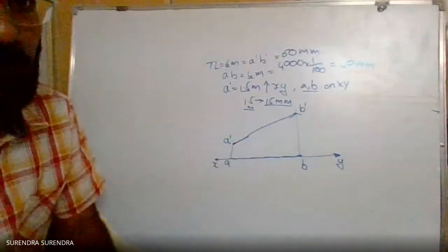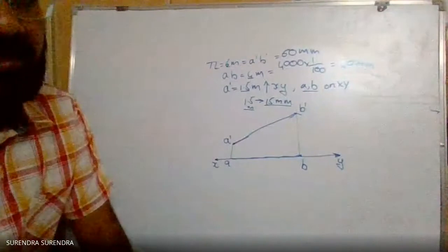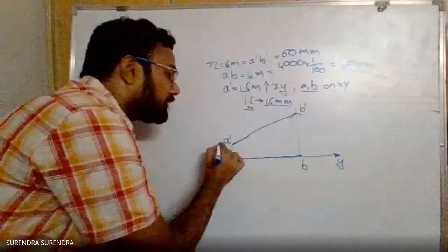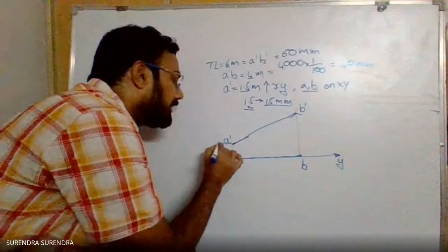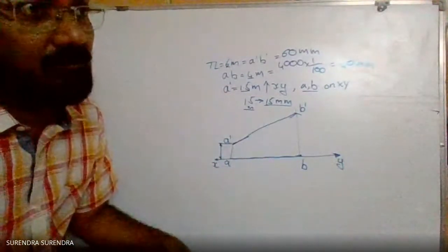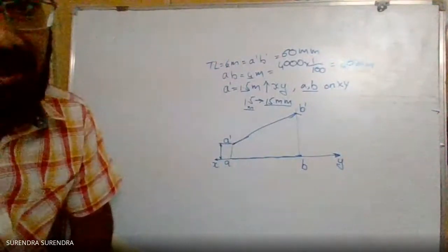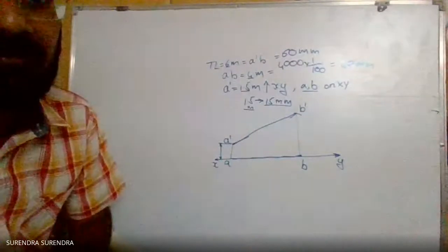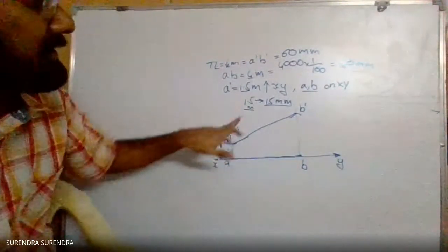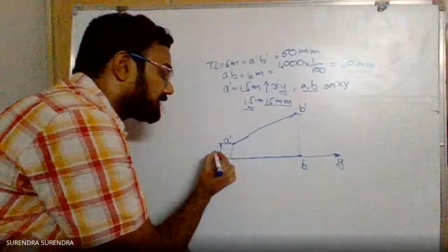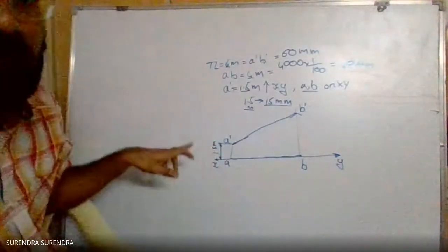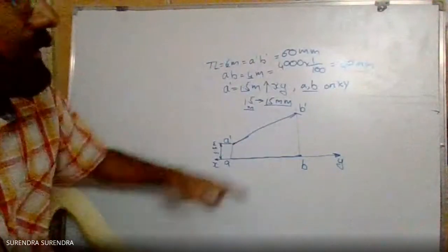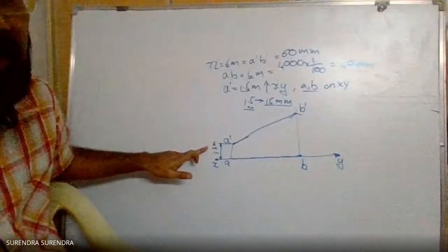And how to represent the dimensions is the most important part, so be careful. The actual dimension is 1.5 meters, and we converted it into 15 mm. Till now, we have simply been representing the dimension values but not the units, because we take everything as mm and, at the end above the title block, write that all the dimensions are in mm. But here the dimensions are given in meters, so for this problem you have to represent the dimensions in meters, as given in the problem, even though the drawing is completed in mm.